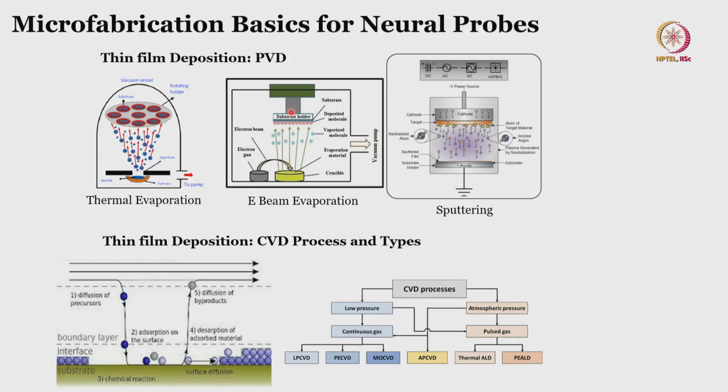Next, again this is using the vacuum. Vacuum is used for increasing the mean free path, remember. The next one is the sputtering unit. In the sputtering unit, we are not actually melting the source material, but what we do is we dislodge the atoms.